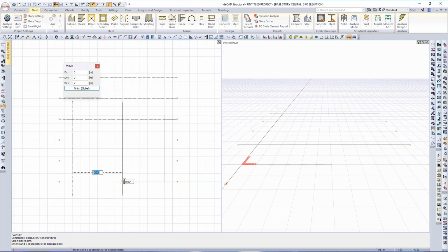A blue field appears on screen to input the distance. You can also press Tab to switch between angle and distance inputs. Since I want to show both portal frame and truss system examples, I'll enter a span of 16 meters, which is 1,600 centimeters. Then I add another span. Let's make it 6 meters, 600 centimeters.